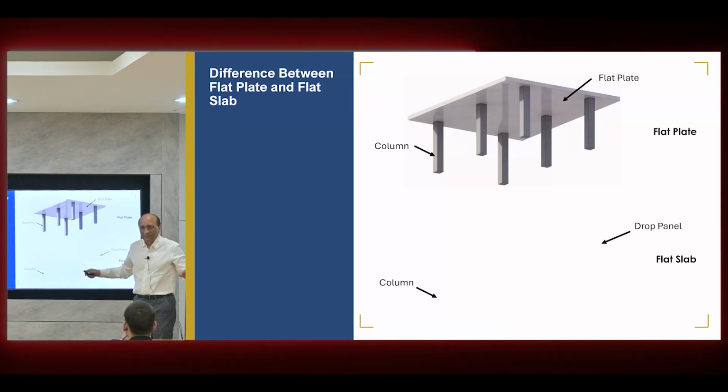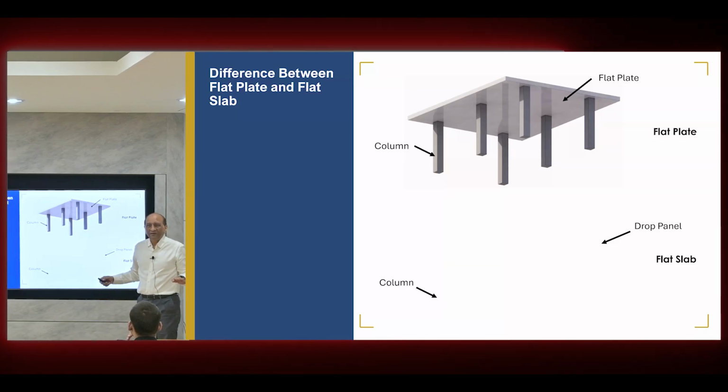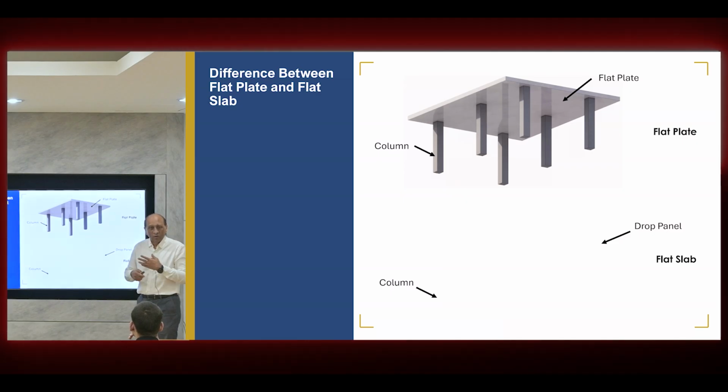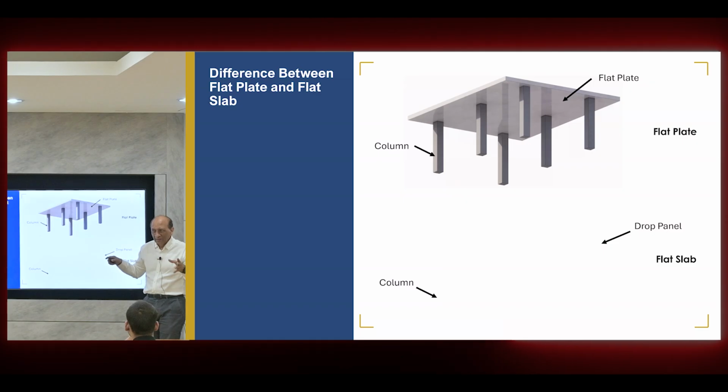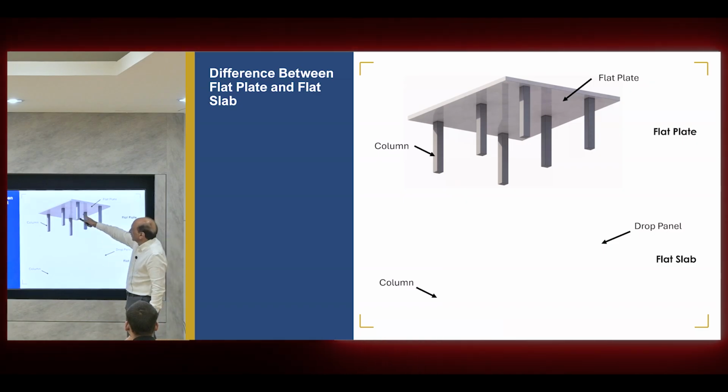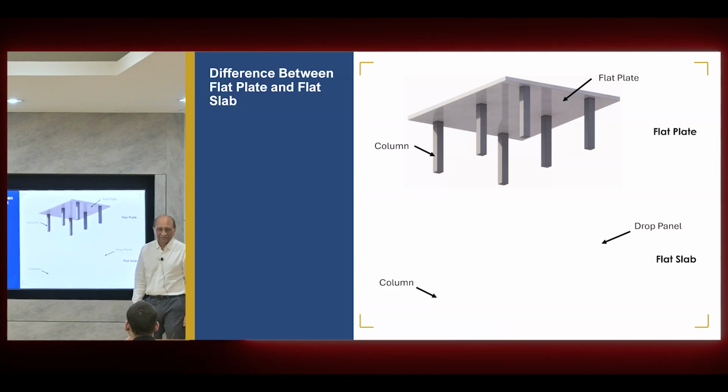They said, get rid of the beams. Let me design a flat plate and get rid of all the beams, which means all the material depth. Now I will just increase the slab thickness, like you said, enough to get the deflection right, but because now it's a two-way system, I can balance many things. This had a problem, flat plate. So this is the first idea, use flat plate.